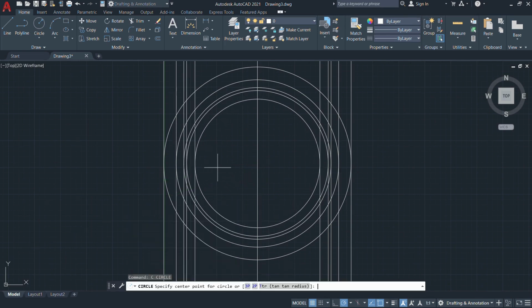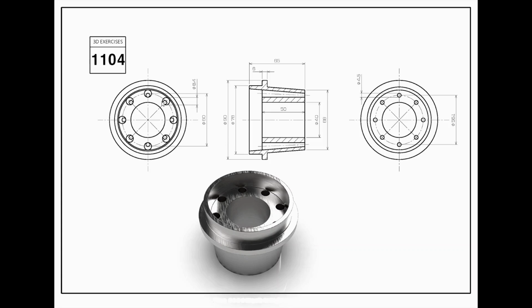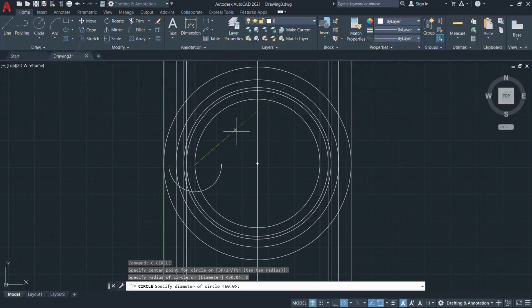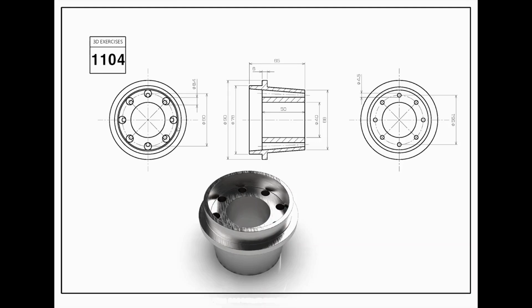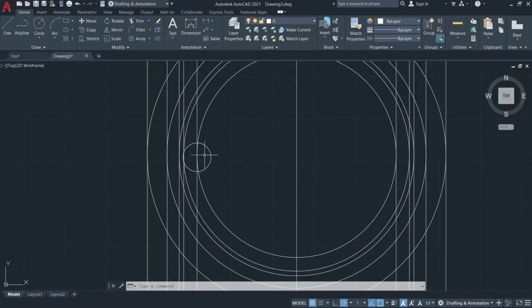Again, choose a circle profile. From the initial quadrant, the diameter is nothing but 8.4 mm. If you look at the picture, it is clearly indicated on the left zone. It is 8.4 mm diameter. Just mention 8.4 mm. Again, we need a second reference, a second pitch circle in this area for drawing a second profile.